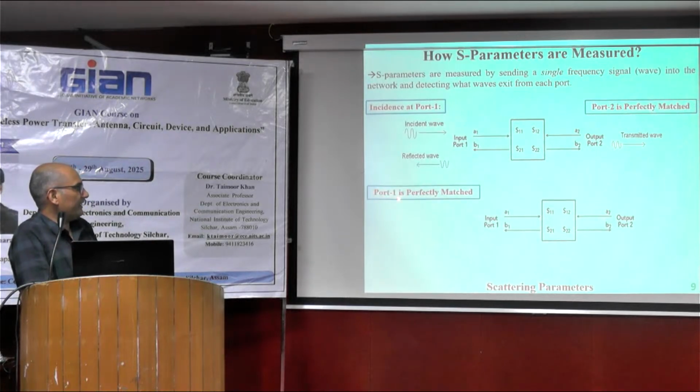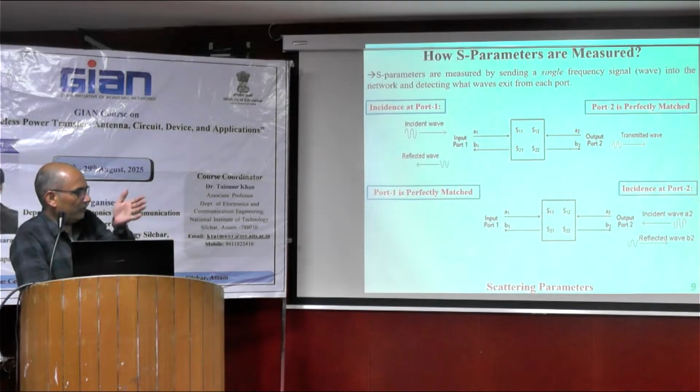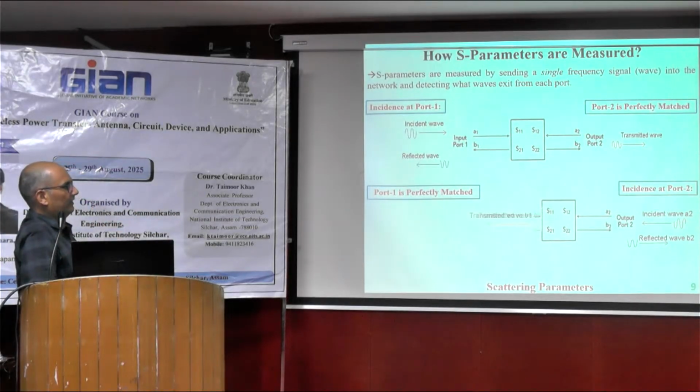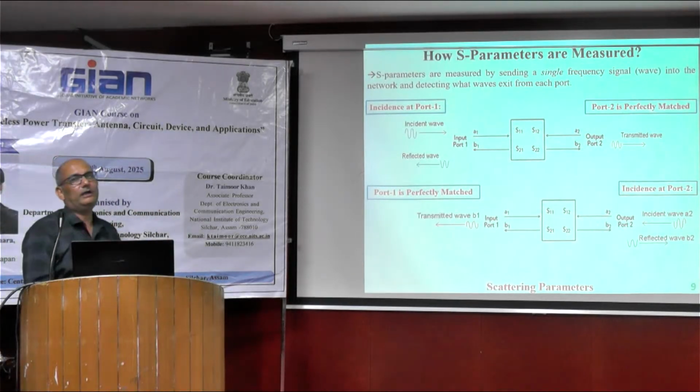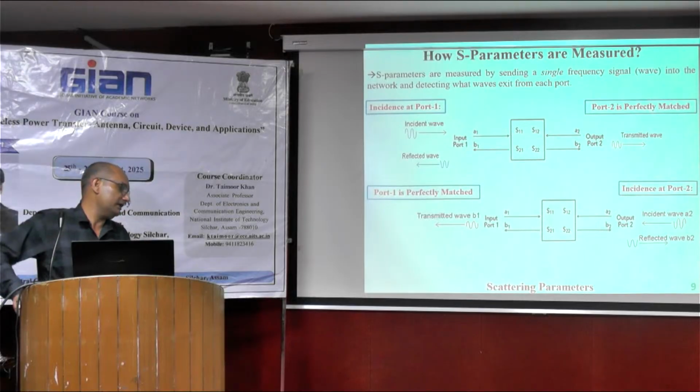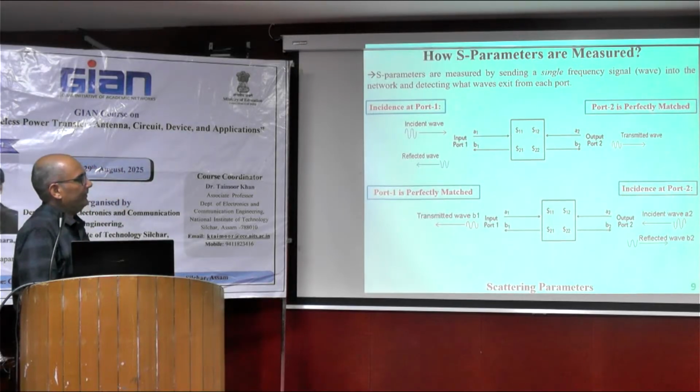Port 1 is perfectly matched, and at port 2 you are exciting with some incidence, like this one, incident wave A2. A part of that will be reflected from port 2, and the difference will come to port 1. That is something we can easily do in a laboratory environment.